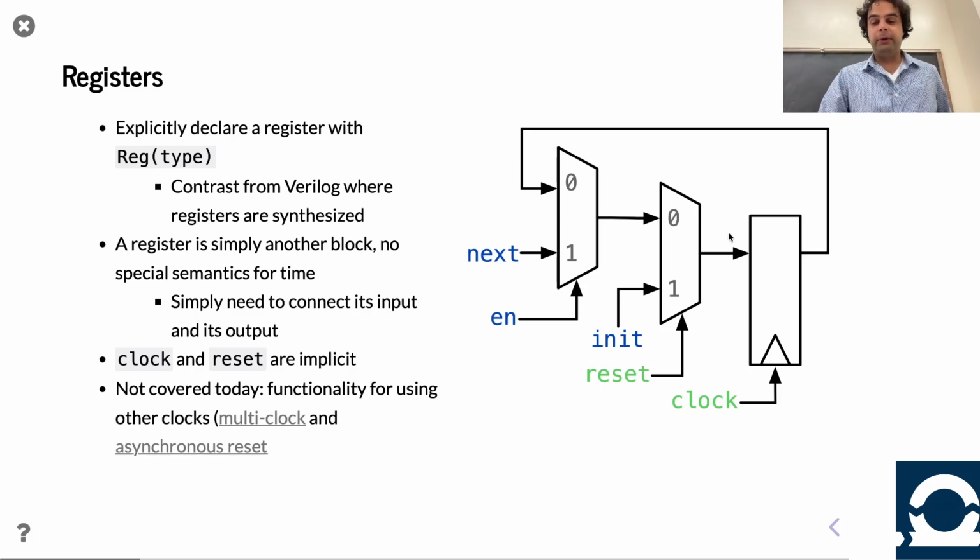So as we're familiar, we have a value going into a register. If it's a normal positive edge triggered flip-flop, that means whenever the clock goes from low to high, a rising clock edge, we take the value on the input, and that becomes the value of the register. And then from then onwards, the register emits that output value. I can change the input at other times, and it won't change the output. It only changes when the clock signal goes from low to high.